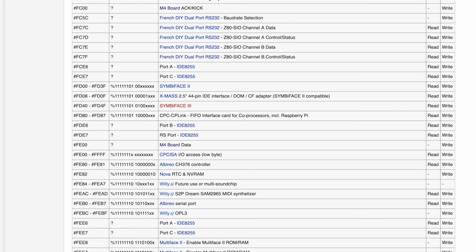Again, looking at the table, it looks like the answer is to also use the lower byte of the address bus. Yes, I know, I said that Amstrad wired only the upper byte, but I was talking about their own chips. As long as you have full access to the address bus, you're welcome to read any part of it and use it to trigger your own activation. And that's what people are doing for the most part. We'll see some interesting exceptions at the end.